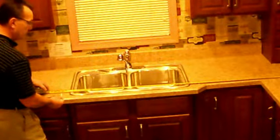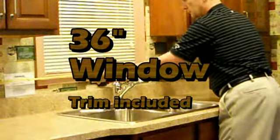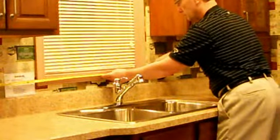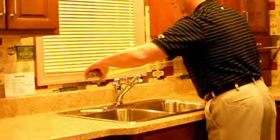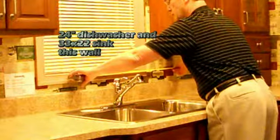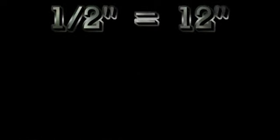And so for our planning purposes, and please follow along and start drawing if you can, this L-shaped kitchen, our window center is 69 inches. The outside to outside dimension of this window is 36 inches. We're going to be using a 33 by 22 self-rimming sink in this, and also a 24-inch dishwasher. So please make notes of the appliances we'll be using. Again, the 36 fridge, 24-inch dishwasher, 30-inch range, and a 30-inch above range microwave.